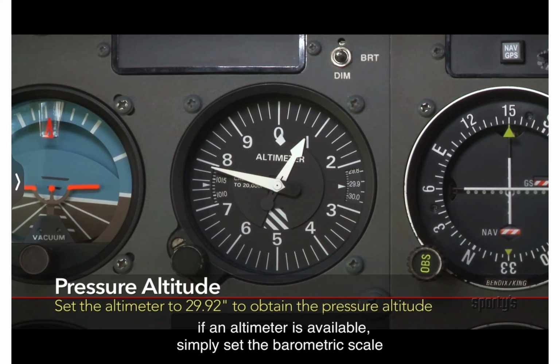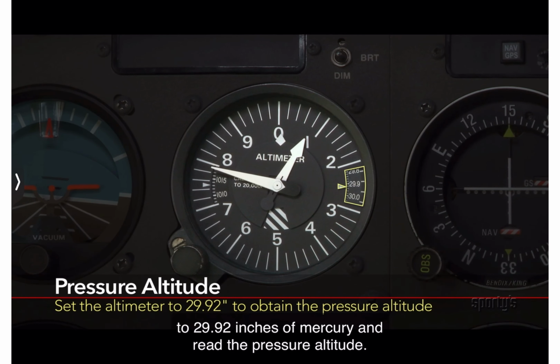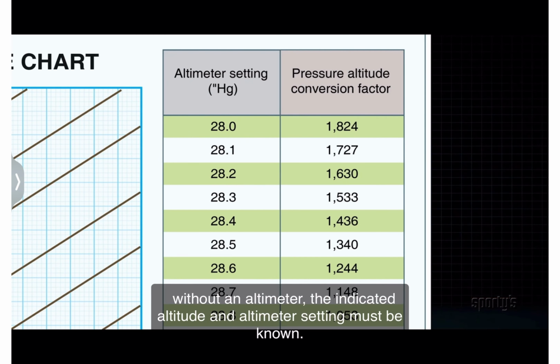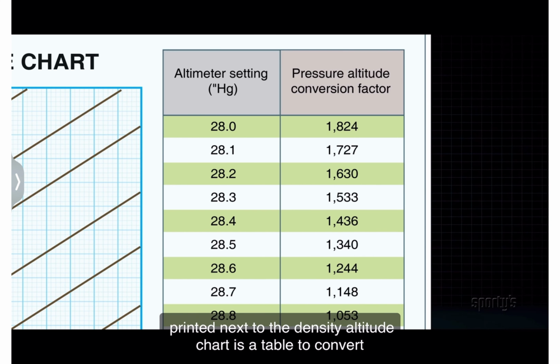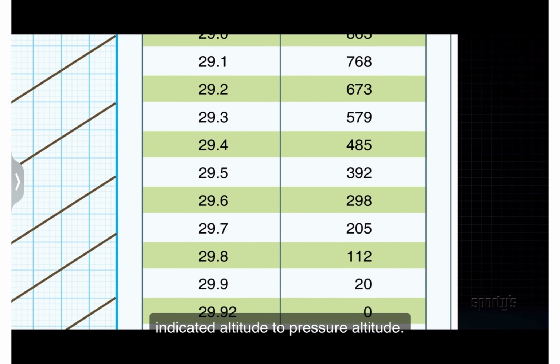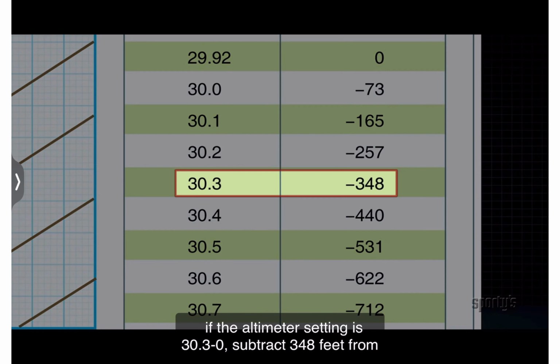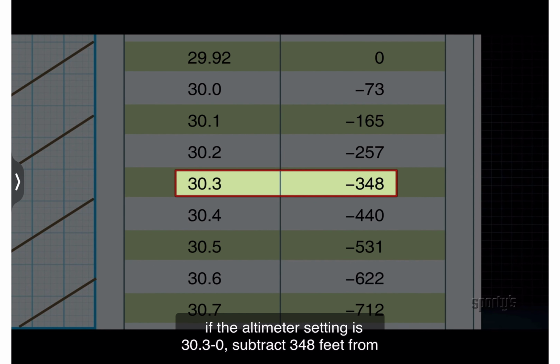If an altimeter is available, simply set the barometric scale to 29.92 inches of mercury and read the pressure altitude. Without an altimeter, the indicated altitude and altimeter setting must be known. Printed next to the density altitude chart is a table to convert indicated altitude to pressure altitude. If the altimeter setting is 30.30, subtract 348 feet from the indicated altitude to obtain pressure altitude.